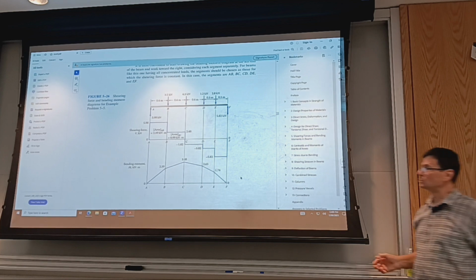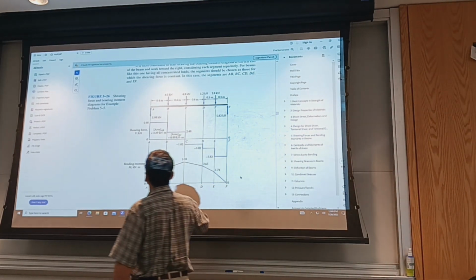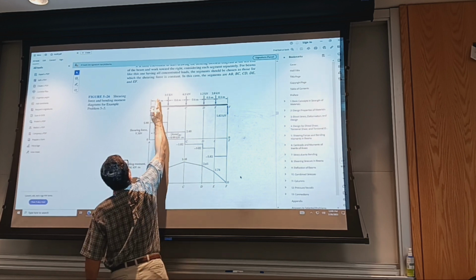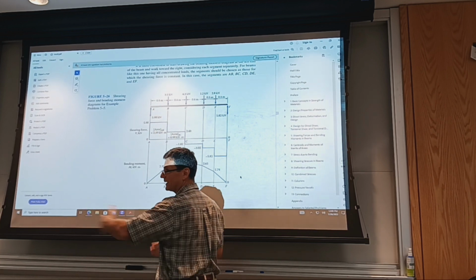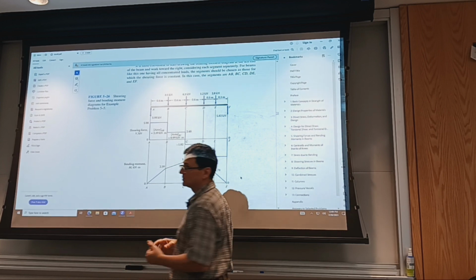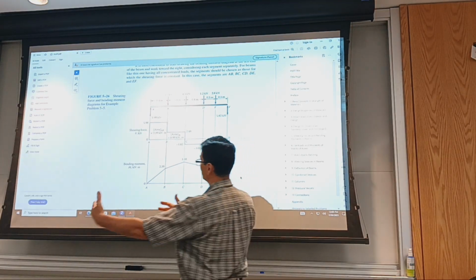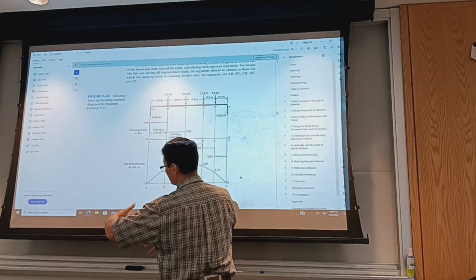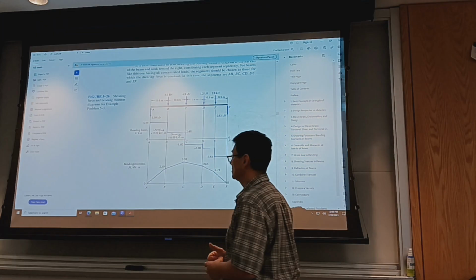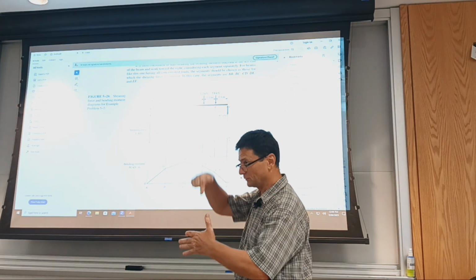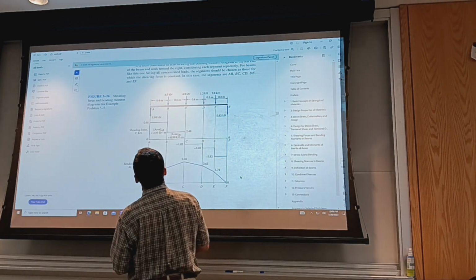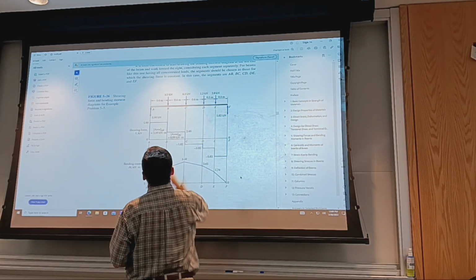And there are some rules that we learned about. So if, working on the left-hand side of the beam, you just section through the beam and do free body diagrams of that left-hand portion where we did the cut, you show the internal shear force and bending moment that holds it in equilibrium together with the externally applied load. So if the shear force on the cross section is pointing down, the diagram moves up.